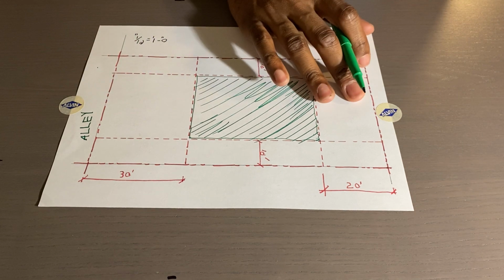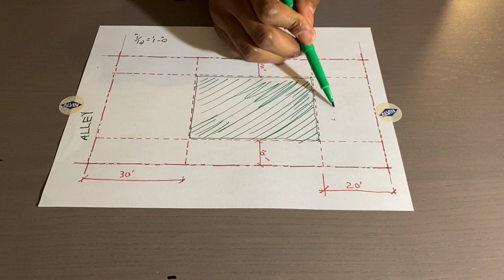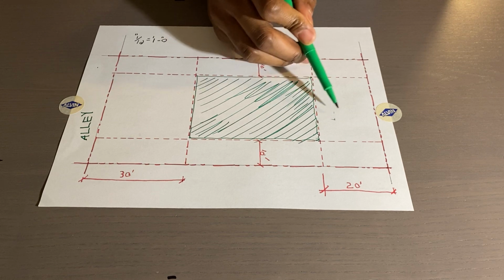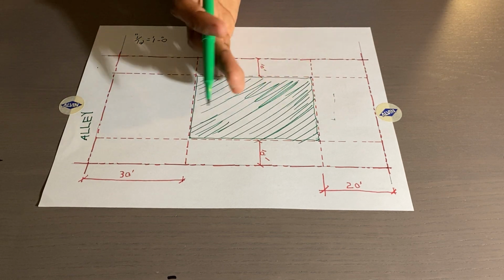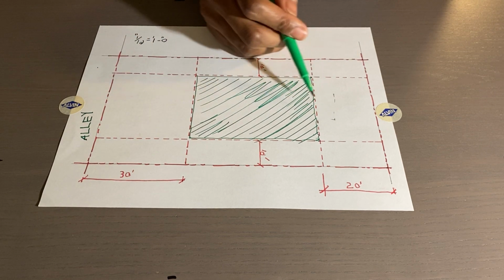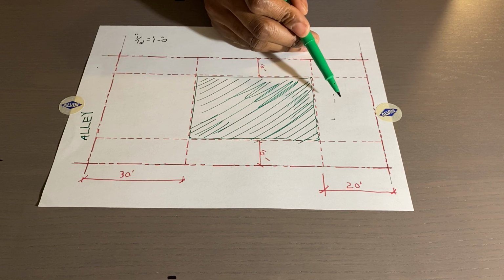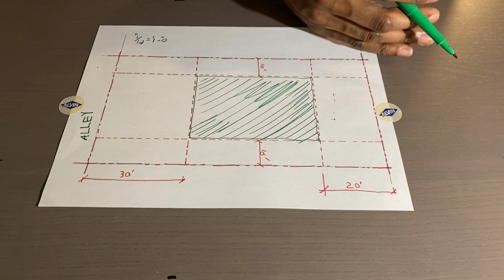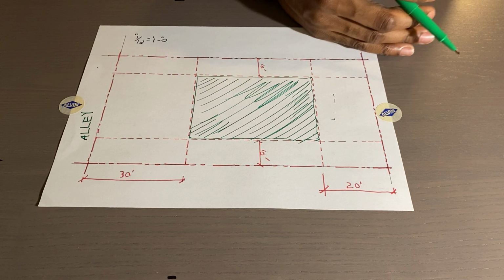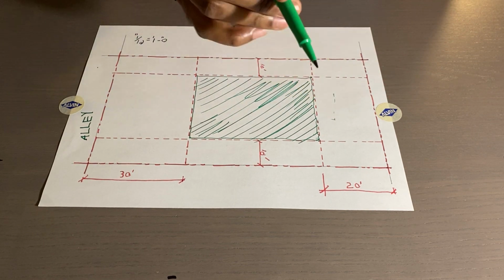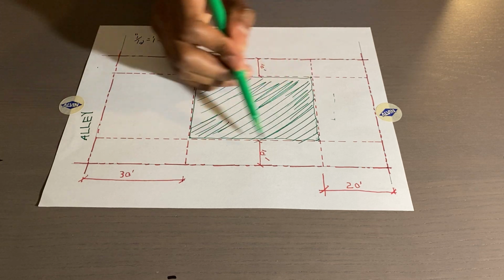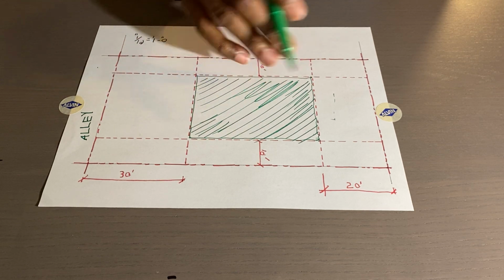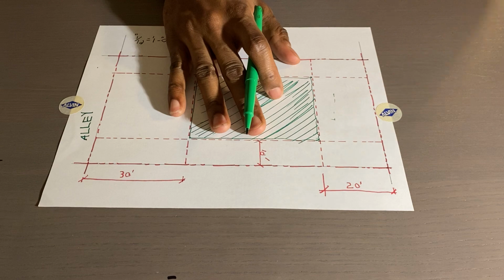And then usually in the front yard, you get an encroachment of some sort, for a porch or things like that. Usually it's anywhere from 6 to 10 feet, depending on what city you live in. But those are the only things that are allowed in the easement area or in the setback area. The primary building has to fall within this line, within this 1,500 square foot area. Okay, so let's remember that as we get into our exercise.